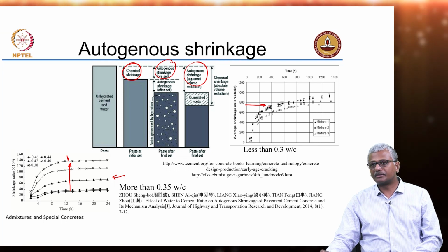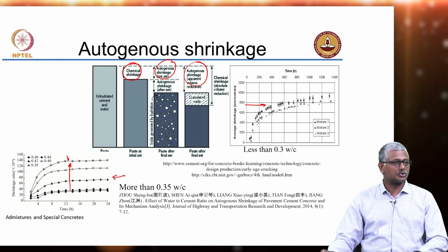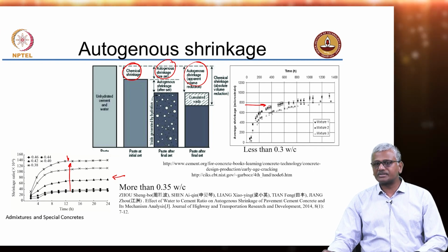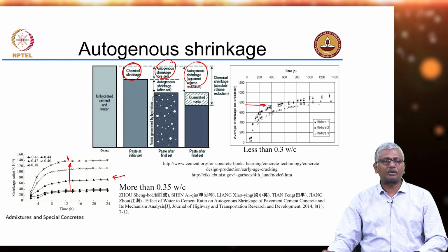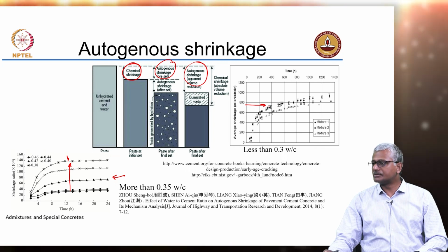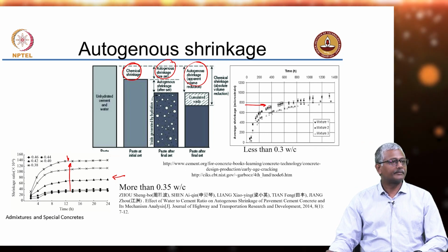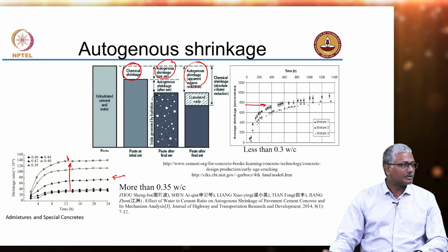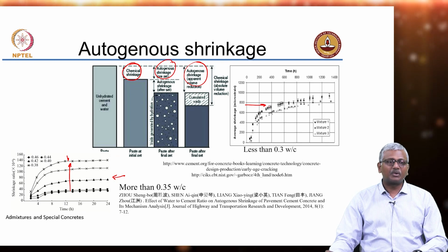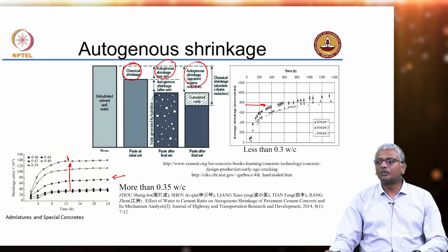If shrinkage is going to be causing cracking, what should you do? How do you prevent it in normal concrete structures and slabs and other concrete members? What is done to counter the stresses that happen due to shrinkage? You can provide joints in the slabs, yes, that is okay, but what if you can't provide joints? What takes care of the shrinkage?